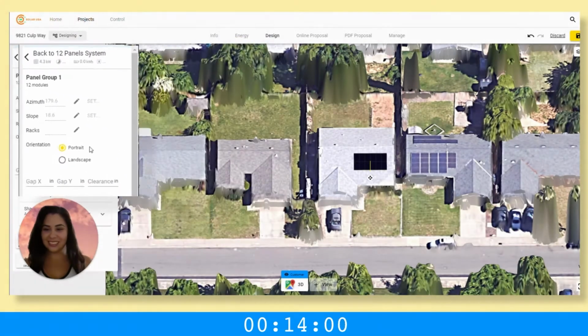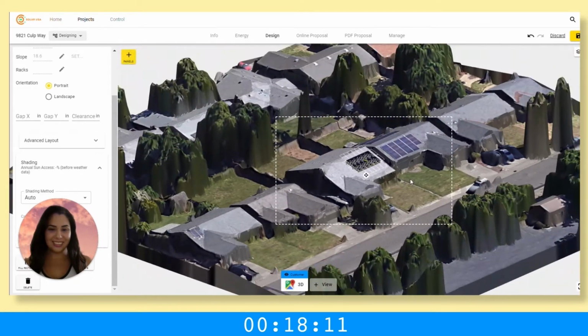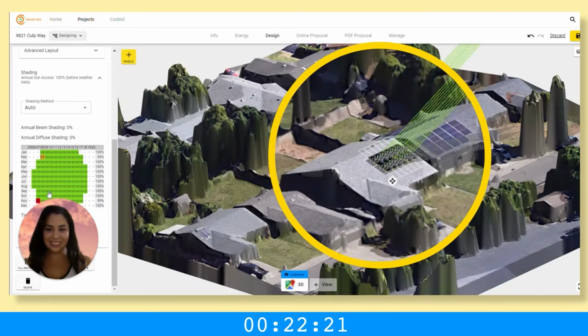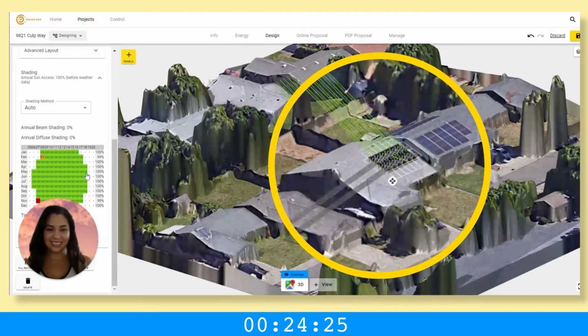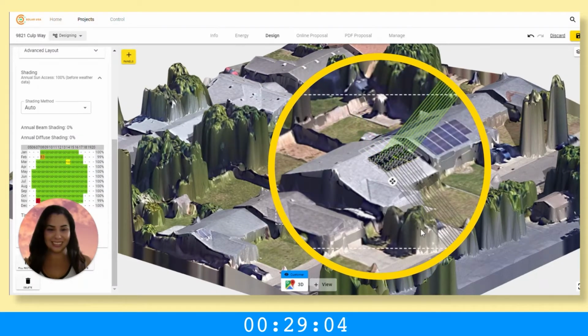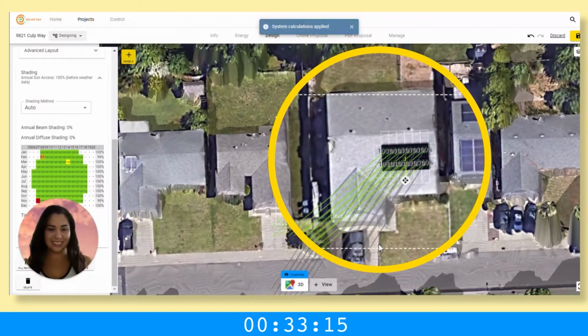Eliomni is loading OpenSolar 3D, which allows us to get accurate and automatic calculations for the azimuth, slope, and shading for the system. She is left clicking and holding to paint her panels across the roof and build her first array. Now she has selected the shading dropdown to access OpenSolar 3D shading analysis. This will help her determine what impacts any trees or obstacles might be having on the system production throughout the year to make sure she's got really accurate calculations on the production, cost, and savings.